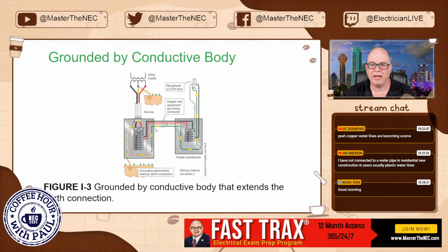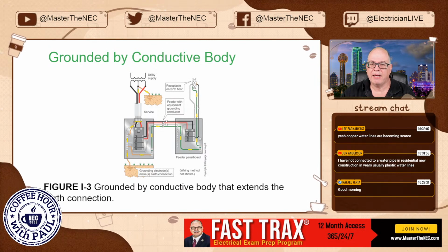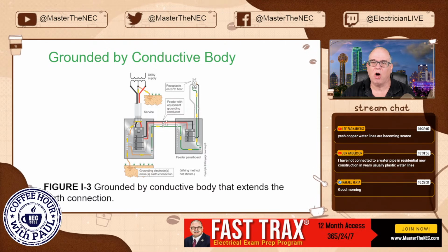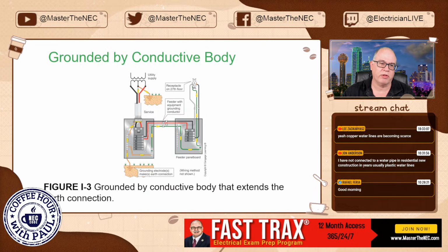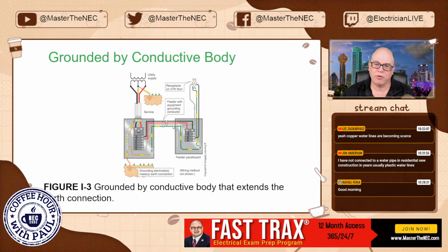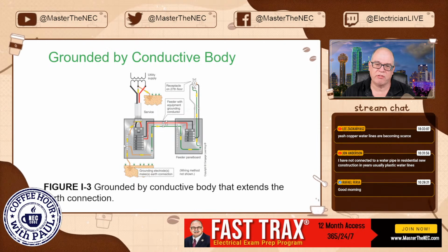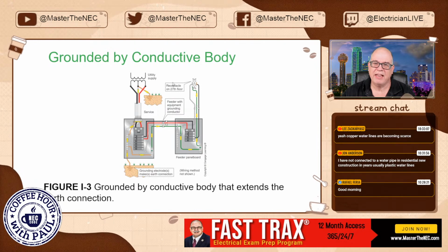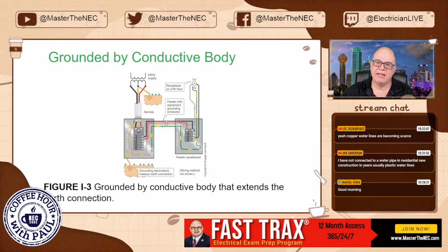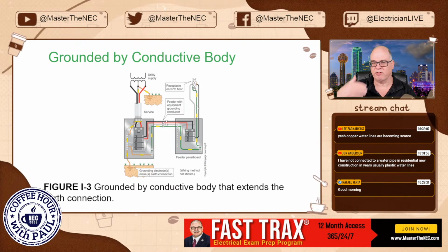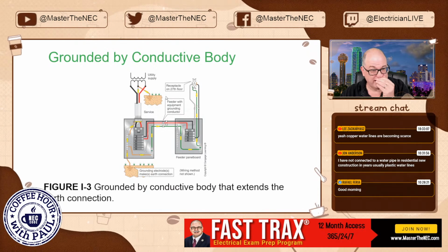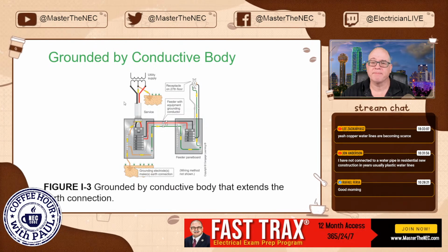So 4 conductors run out there, okay? And here you see that the actual equipment grounding conductor extends that path all the way up to the receptacle on the 27th floor. So there's your connection down through the bus, over through, down here, through that main bonding jumper, back over to the neutral, back to the source. That's what's going to allow the overcurrent protective device to clear if you have a fault down here at the receptacle point location, okay? But that is extending the connection to earth.